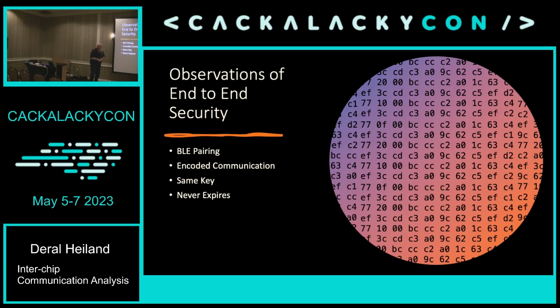Some of the things we're trying to figure out around this, observations: there is required BLE pairing. In another device that I was doing, another product lock which I did for a vendor, I was actually able to force, through interchip communications, the device to pair to someone else's lock. Obviously, they fixed that, which drove me to dig into some other locks to see if other people were having that problem. Encoding communication, but it's the same key. It never changes. It never expires. So we get that level of observation.